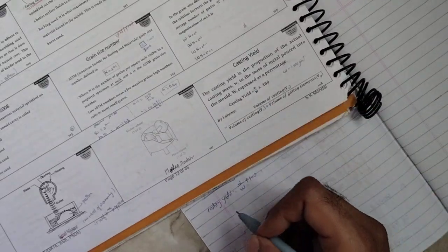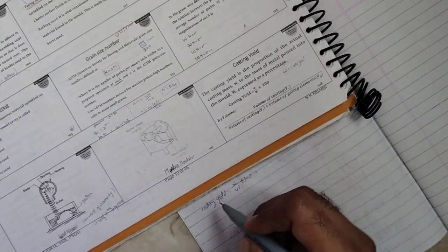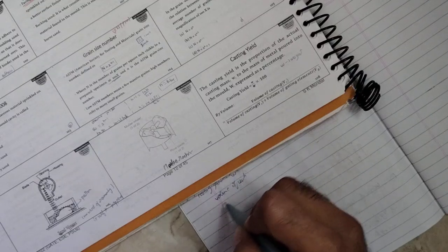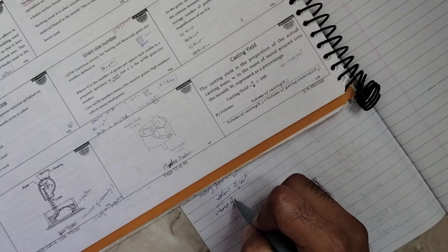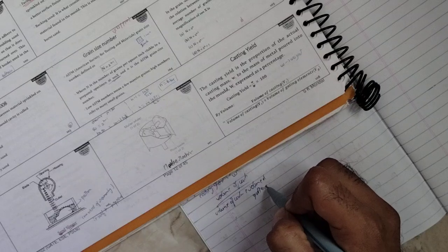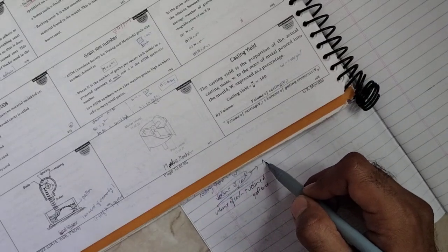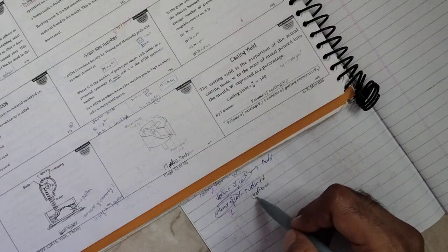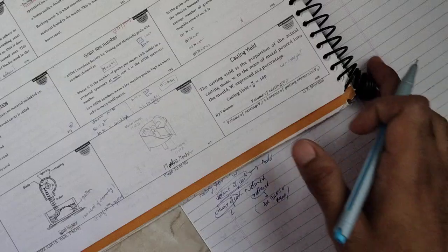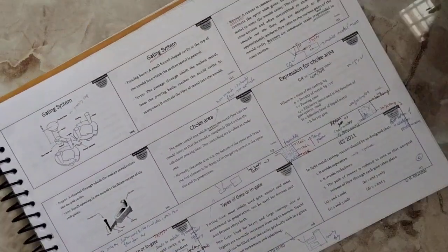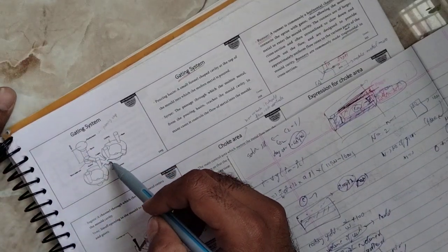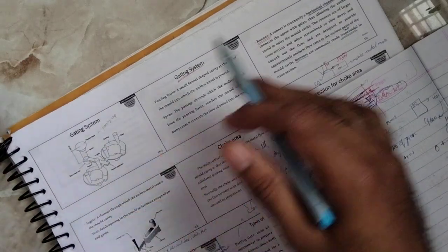So what is W? It is the weight. In the upper portion is the weight of casting, or the volume of casting, divided by the volume of casting plus the volume of the gating elements. The volume of casting is the main mold area, what we need. The rest is the sprue, runner, ingate, as well as the riser. Next, you can see the pouring basin, sprue, ingate, the casting area and the riser. We need to consider all of these.